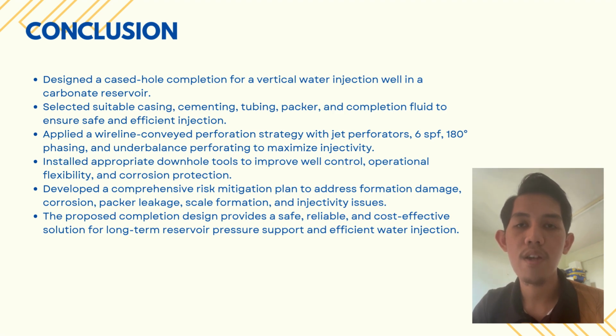In addition, we developed a comprehensive risk mitigation plan to manage potential issues such as corrosion, formation damage, packer leakage, scale formation, and injectivity decline. Overall, the proposed completion design provides a safe, reliable, and cost-effective solution that supports long-term reservoir pressure maintenance and efficient water injection.